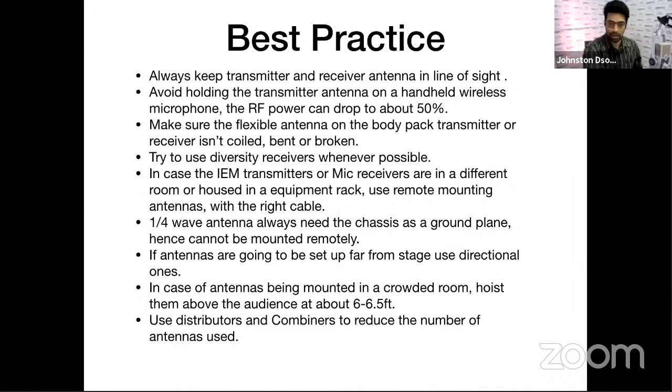Okay, now if they are very particular about the look and feel of stuff, do not use your fish fin antennas and stuff which are usually black in color. You can go for wall mounting antennas. Mount them on the wall, on the ceiling, and they'll pretty much be invisible, or at least they'll get camouflaged with the paint of the wall.